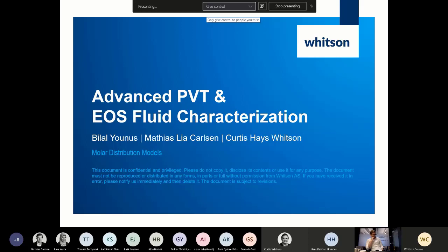Very good. Remember to always back calculate based on measured molecular weights and specific gravities, such that we capture that potential change that Curtis talked about, from potentially a more paraffinic fluid to something that can be very aromatic in this case, or something slightly less dramatic as well.